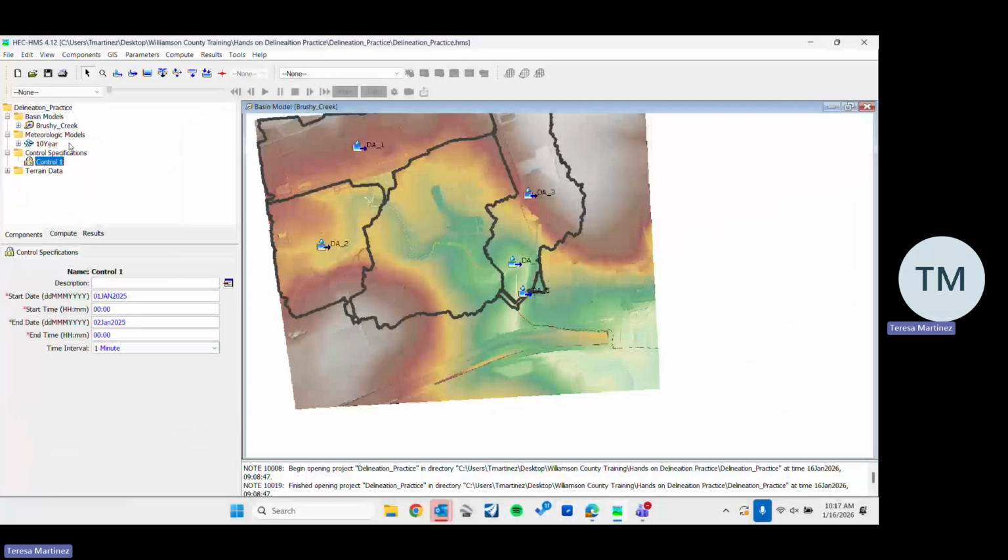What is the start time and end time doing? Because I can see we don't have any time in there. What would that have actually been, like 8 a.m. to 3 p.m. the next day or something like that? Is it using it for anything other than the output header, maybe? When we look at the hydrograph, you know how it has a time on the x-axis? It's basically telling you that storm duration for that hydrograph.